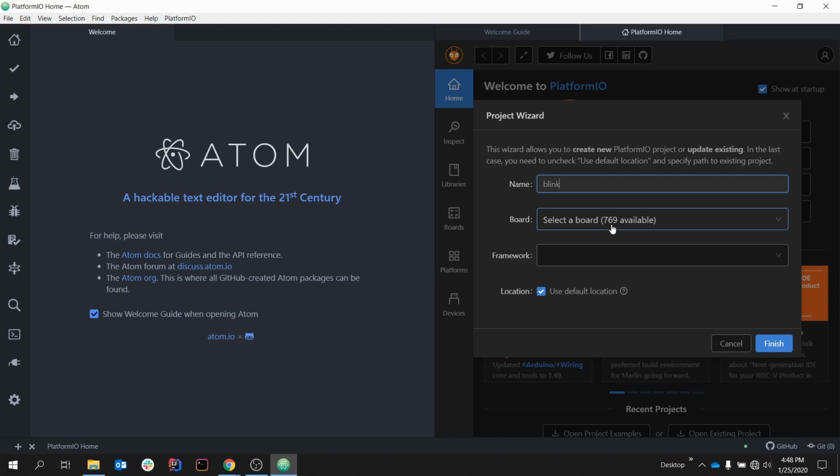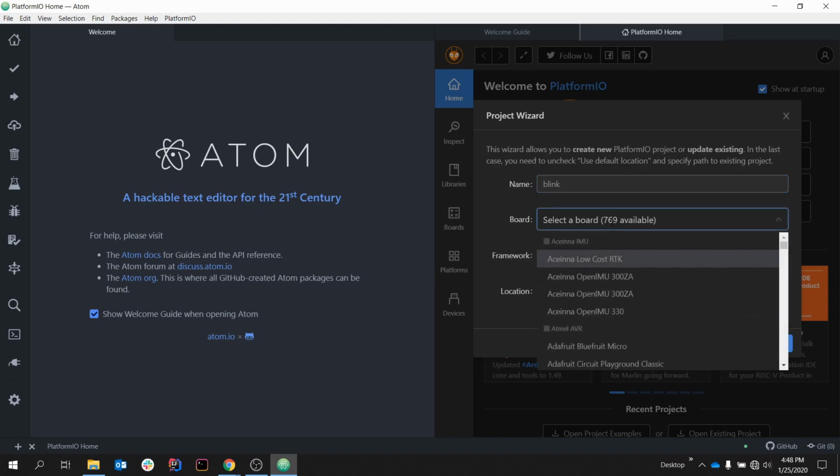If you wanted to use a Teensy, you'd have to download the Teensy Arduino installer. You'd have to run that with the Arduino IDE, and they'd have to run in tandem. Whereas with the Atom and using PlatformIO, you don't have to do any of that. It downloads whatever additional software you need for you, and it already has the board in it.